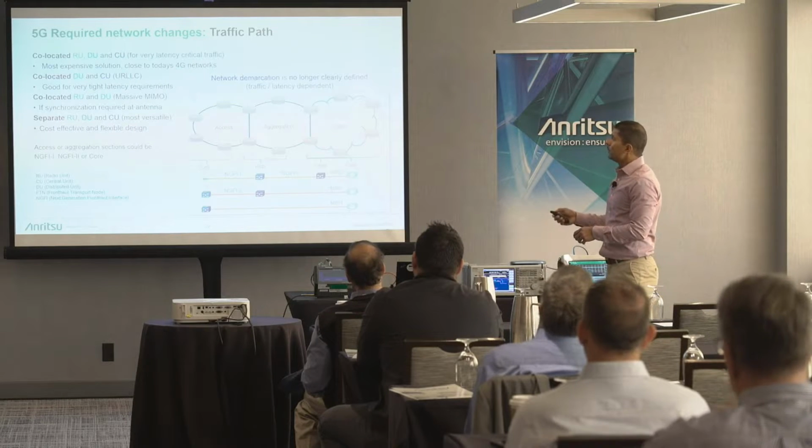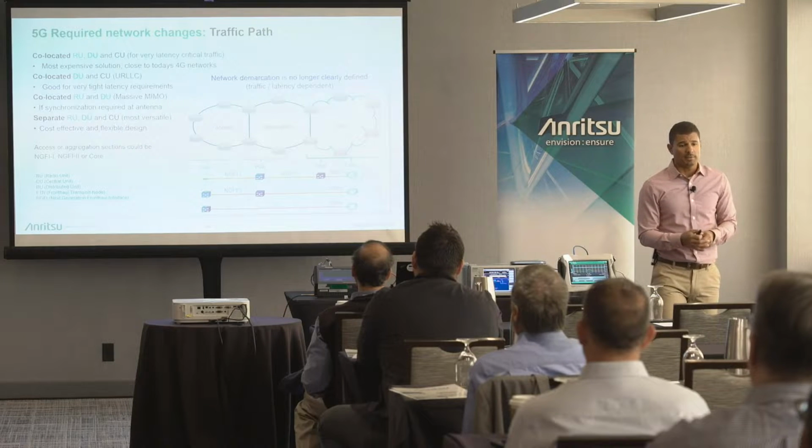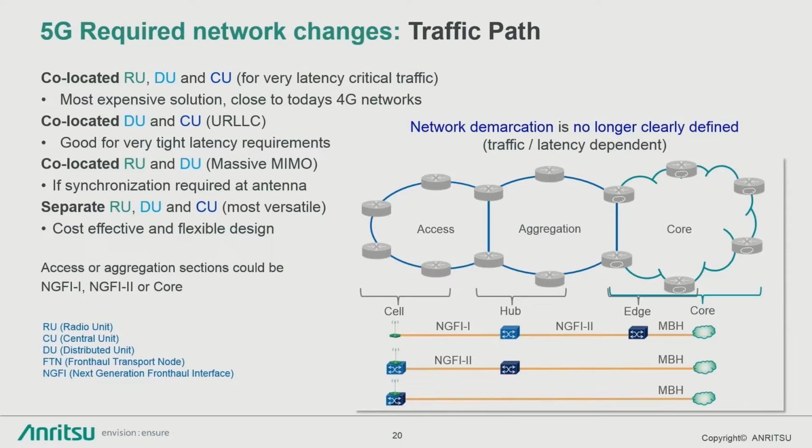Okay, so this is kind of summarizing this, and this is the question I propose here. In 4G we had the BBU, and we're taking the functions of that BBU and turning them into logical entities, software, for the DU, where it can terminate my eCPRI and my IQ data, and the other half, the CU, where it's distributing all of my user data out to the network.